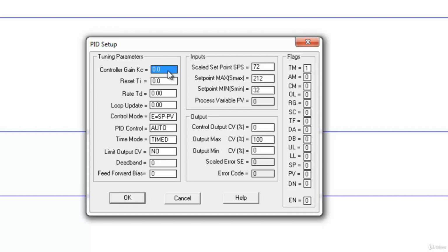And if you don't know what oscillate means, that means your temperature is going to go a little bit above the set point, then it's going to fall back down a little bit below the set point, maybe, or it'll just go a little bit above and fall back to the set point, depending on how powerful your heater is. But it's going to be going up and down eventually. And once it starts going up and down on a steady basis, we're going to cut that value down. I know it said to half of the oscillation, but we're going to cut it down to 2/3 of whatever set point we had in there to make it oscillate.